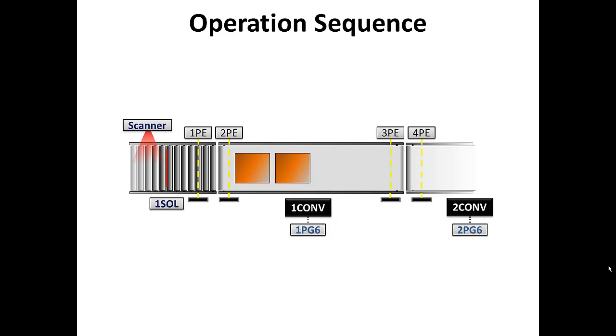The first carton on is going to move away at full speed, but it may take a few seconds for the belt to fully grab that second carton and get it onto the conveyor belt, plus the spacing between the photo eyes. So if the photo eye 2PE was to be moved a little bit further to the right, then each carton would be a little bit further onto the middle buffer conveyor before the conveyor stopped.